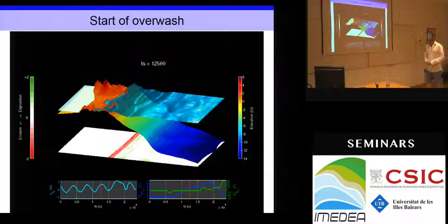The grid resolution. Actually, the grid resolution varies. Because we're modeling the infragravity waves, they have longer length scales in deeper water. So the grid resolution in deeper water is larger, so that could be like 25 meters or so. And then it gets to a couple of meters close to the coast. So overland is in that order. And in the alongshore direction, the grid spacing is about in the order of 10 meters.